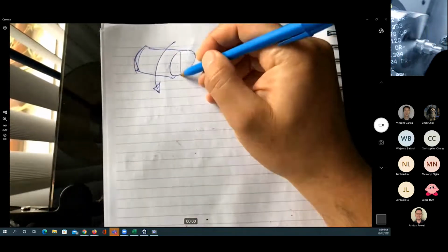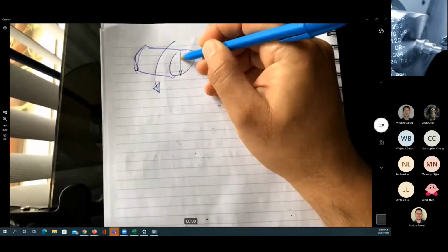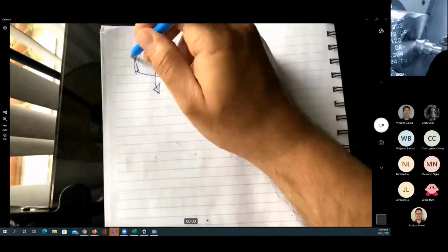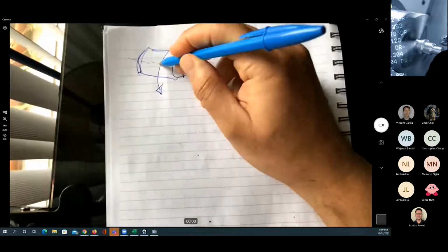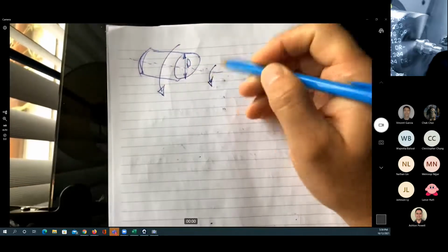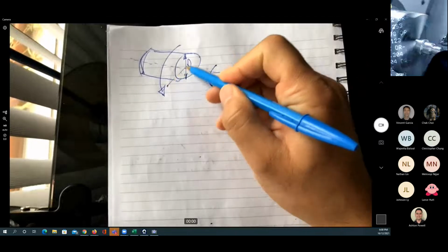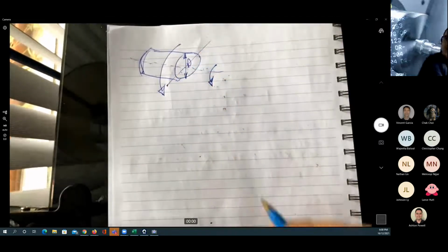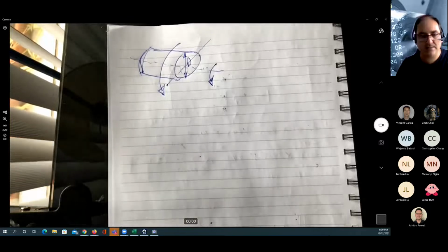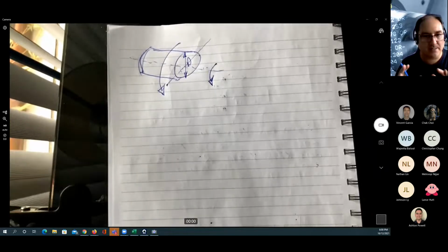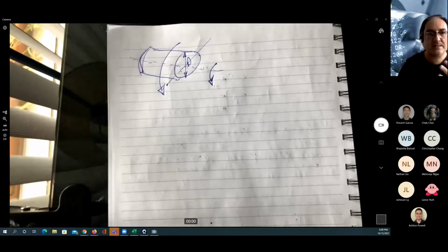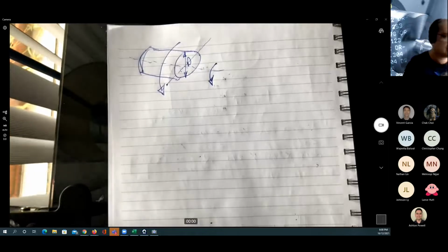So if this is the diameter of the work part D, this will be the center line of the work part, the center of the rotation. And we have another axis here. Now, we have to learn that everything rotating in the operation of machining in general, not only turning, milling, and drilling, this axis will be the z-axis.